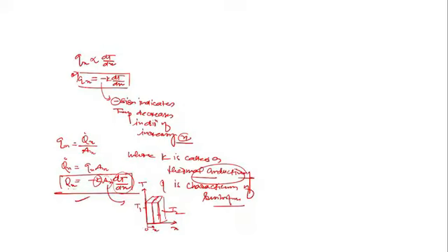At any x, the area normal to the direction of heat transfer is Ax. Clear? And the temperature gradient at this point is, let's say, dT/dx. The temperature gradient may change from location to location, depending on the conditions. It is the slope of T versus x. Yes or no? So dT/dx is negative, but when I multiply it with the minus sign, it becomes positive. That's why I write it here in terms of q. That will give you the positive rate of heat transfer.